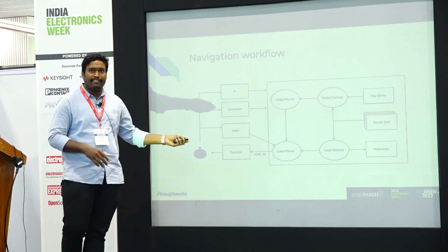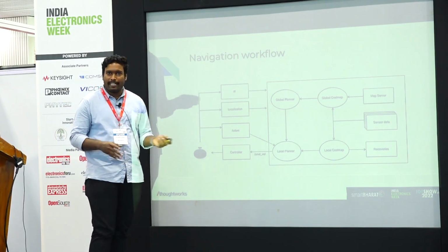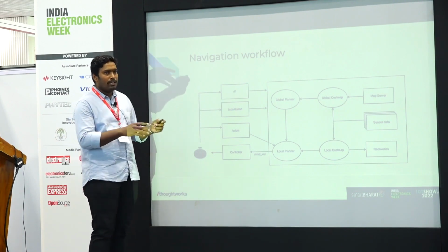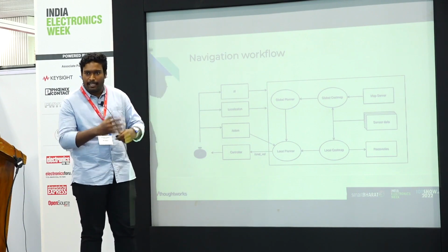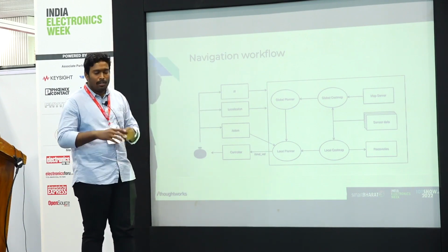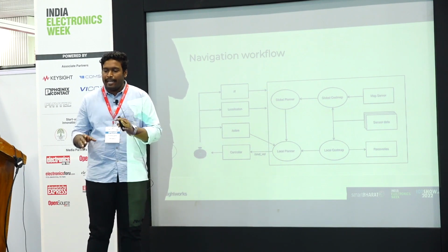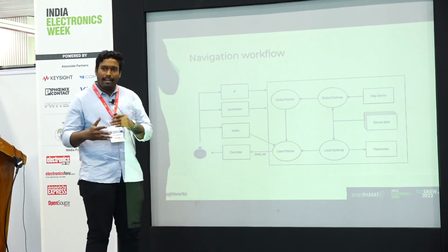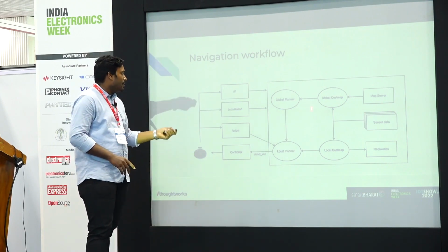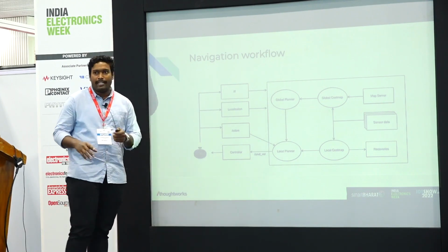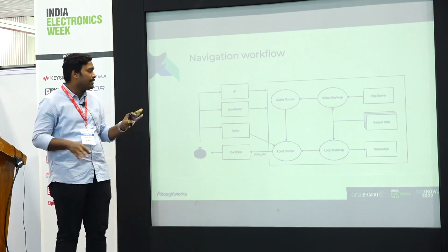So you can receive that information from your sensor data, and you can also define some recovery behaviors, but that's not covered in depth here. Based on the local environment, you have a local cost map. A cost map is just an enhanced map: you have some dynamic real-time information and you add it, and you also have a global cost map that adds additional information about the whole map that you generated in the SLAM.